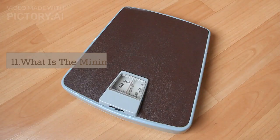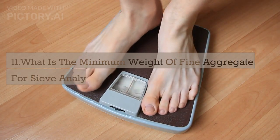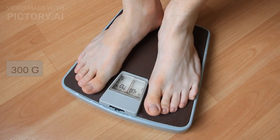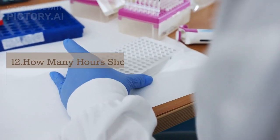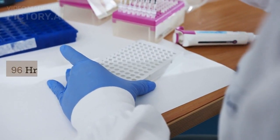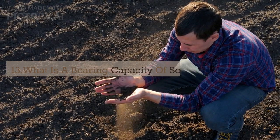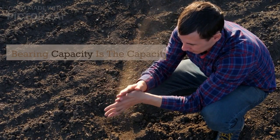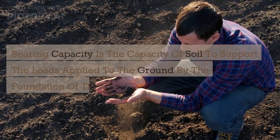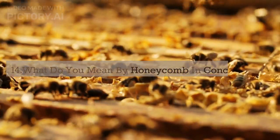11. What is the minimum weight of fine aggregate for sieve analysis as per ASTM C136? 300 grams. 12. How many hours should CBR samples be soaked? 96 hours. 13. What is a bearing capacity of soil? Bearing capacity is the capacity of soil to support the loads applied to the ground by the foundation of the structure. 14. What do you mean by honeycomb in concrete?